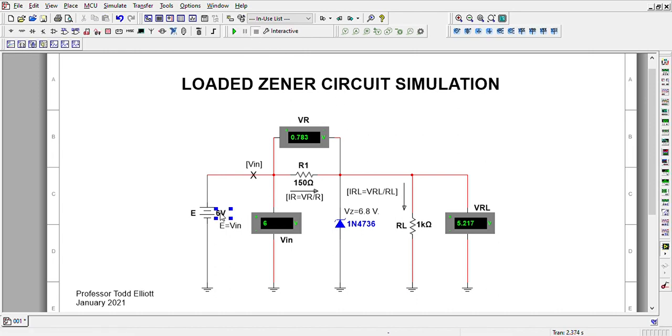So if we were to just put it to VZ, you're always going to want it more, at least several volts more. We're just going to see what this does. Even that is not high enough to have the Zener sufficiently reverse biased. So let's put this back to 9, and then we're going to hit start. And everything's back to normal.